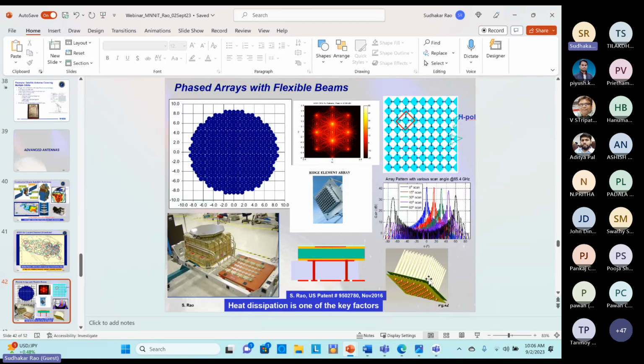So probably that's more suited to you, maybe a small portion of this array to feed your reflector to give you the right taper at the low frequency. At high frequency you get a good taper anyway. At low frequency, you need to combine those signals anyway. I don't know whether you're doing the beamforming digital or RF or IF, so it all depends on technologies. But antenna-wise, I think those can give you 0.2 to 2 gigahertz, which is a 10 to 1 bandwidth ratio. Some form of Vivaldi. You can try the ridge element also, because that's designed for 8:1 bandwidth ratio. Maybe you can extend to 10:1, because that's much more compact than Vivaldi, because Vivaldi tends to be too long, right?